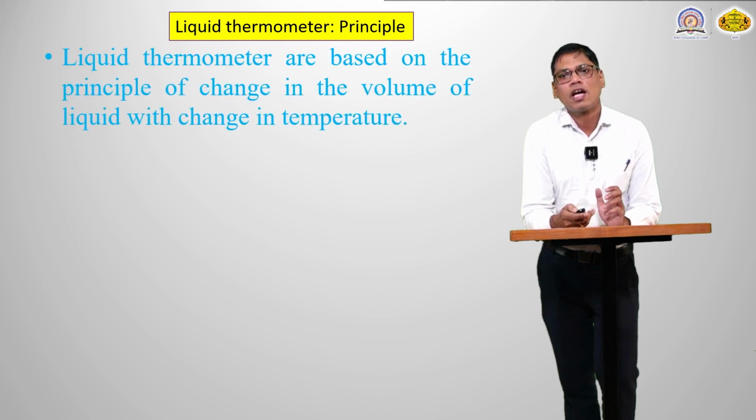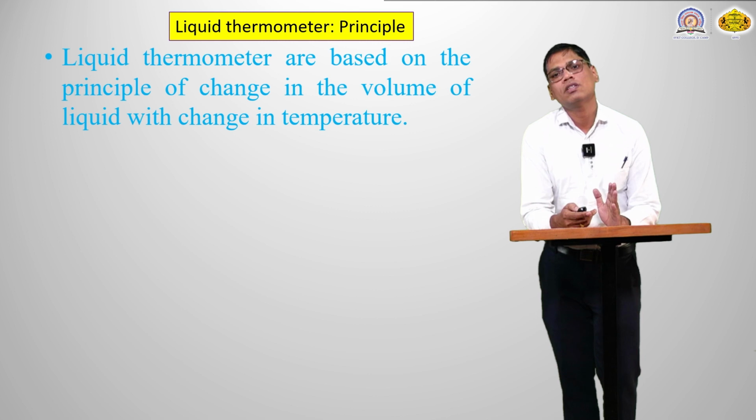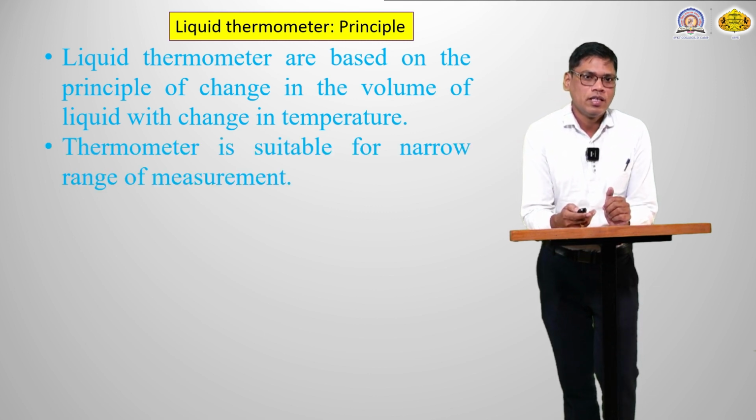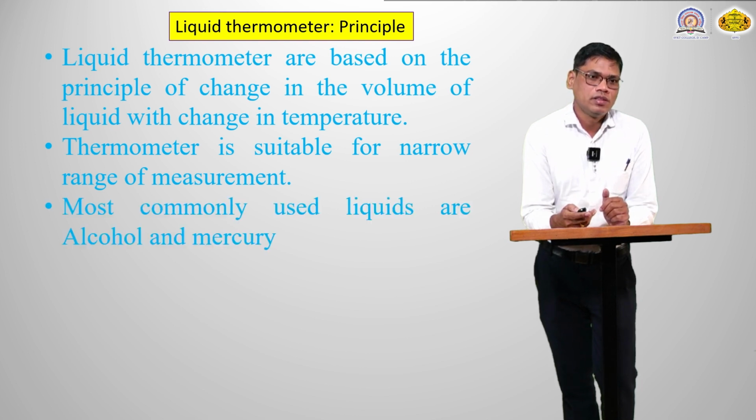Liquid thermometers are based on the principle of change in the volume of liquid with change in the temperature. Means if the temperature of the liquid changes, then the volume of that liquid changes. This thermometer is suitable for a narrow range of measurement.